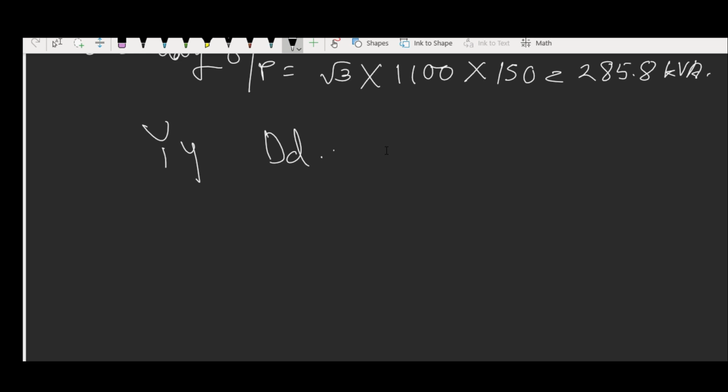However, line current and line voltage have also maintained that ratio. Like if your primary current is 15, the secondary current becomes 150, even if we consider the line current. That is because both the primary and secondary have identical interconnection. But if we consider star-delta, then we will have a different result.